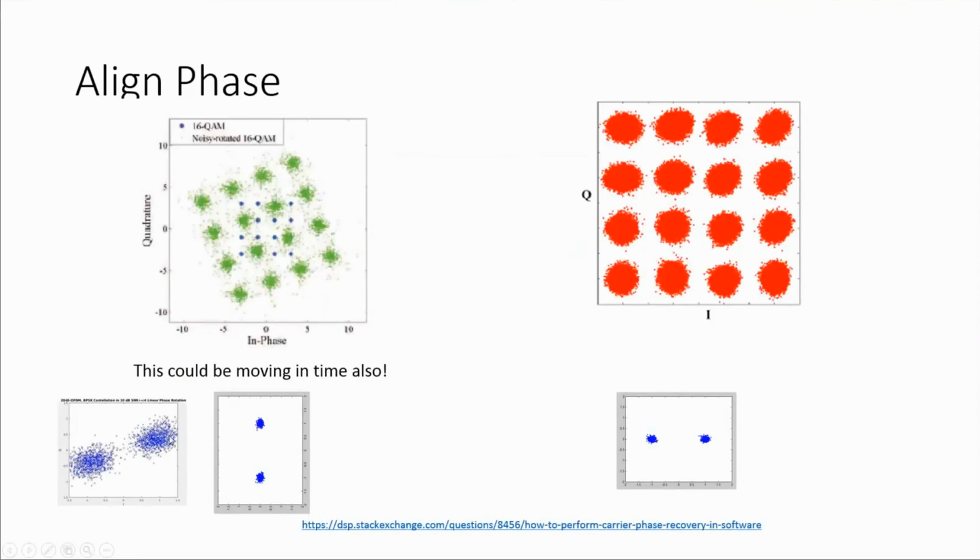Here's another example of a noisier one that's on an angle. This is a cool example. If we had BPSK that was perfectly phase aligned but 90 degrees out of phase, since we're only bit slicing in these regions, we'd actually get no data at all, even though it's obvious that we have a very high signal to noise ratio. So it's really important that this is rotated such that if we put our bit slicer here and we say, is it here or there, that we can see something, versus if we put our bit slicer here, we just get nothing.